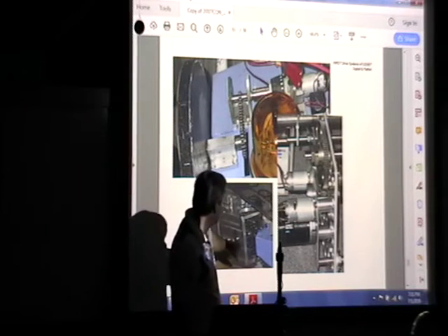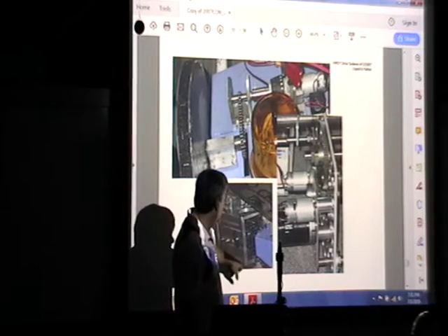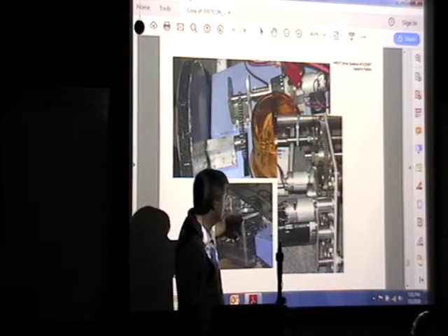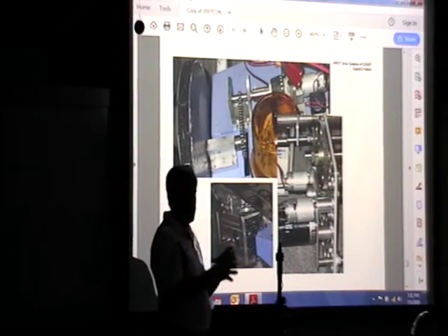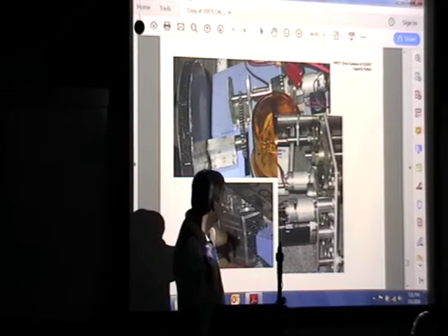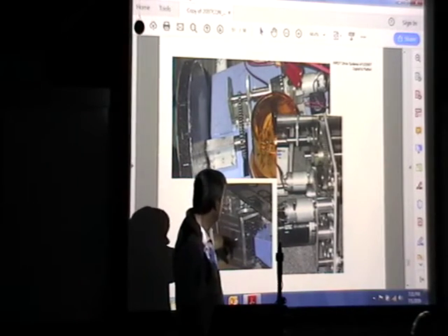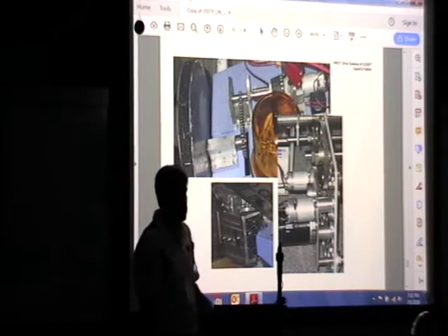I'd be curious in this case how they got those two aligned, because it looks like that's an assembly. There again, you gotta consider the fact that these just being bolt heads, there's some clearance in bolt heads, right? So you gotta make sure that if these are changing in any way, that your misalignment of this bearing to this bearing isn't causing trouble.